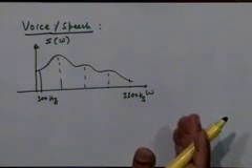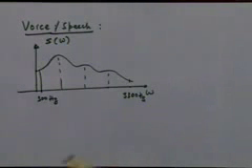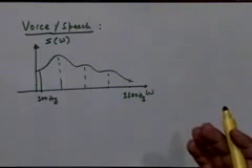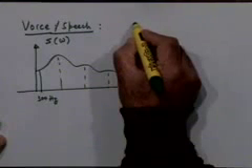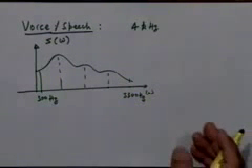So for most telephonic communication purposes, the band from 300 hertz to 3300 hertz is the one which is important, right. So that is why we say that a voice band channel has a bandwidth of about 4 kilohertz. That 4 kilohertz includes some guard band, some additional frequency band, to make sure that we don't lose anything, right. So typically the bandwidth of a speech signal is regarded to be less than 4 kilohertz.